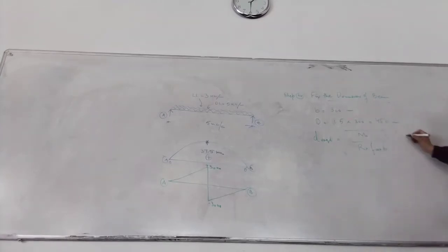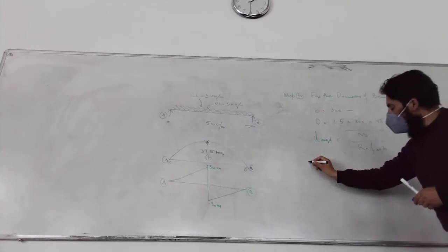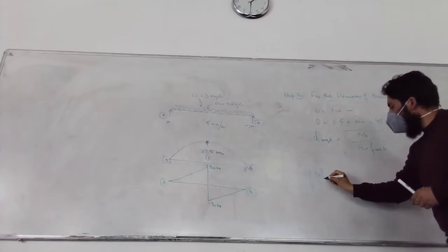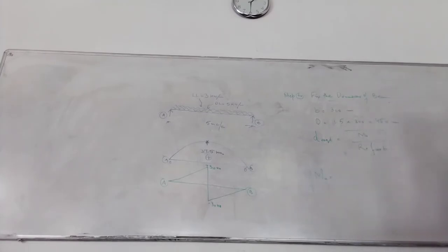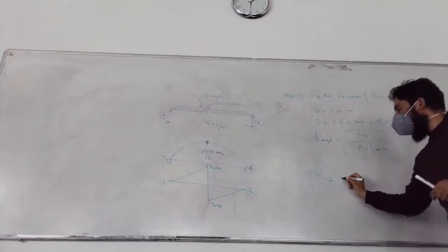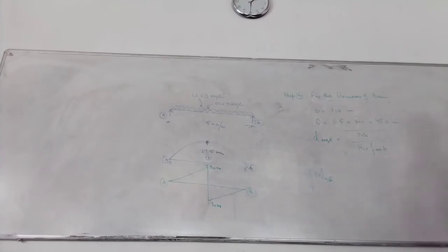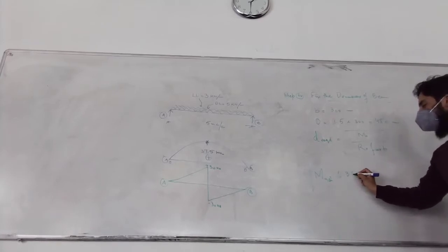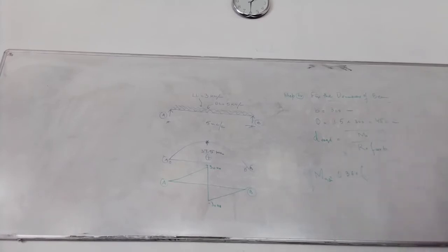Did we see an equation last time where Mu was the ultimate limiting load moment? What was it equal to? There was an equation given in the code at the end. Can you recall that equation? It was 0.36 XU max by D